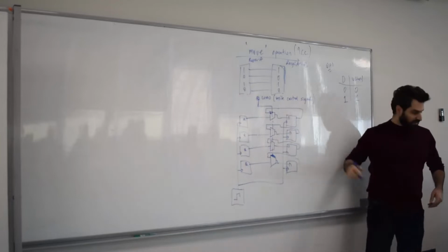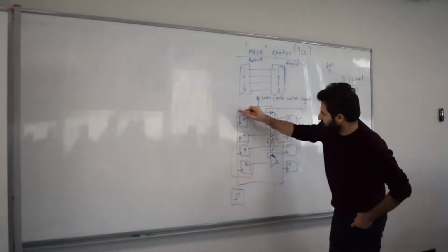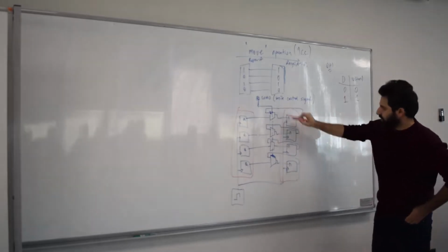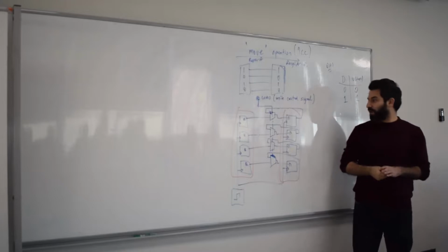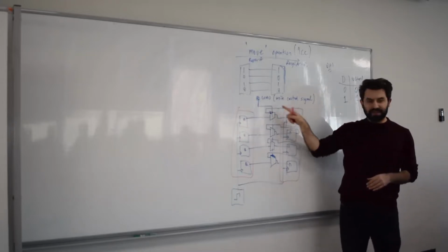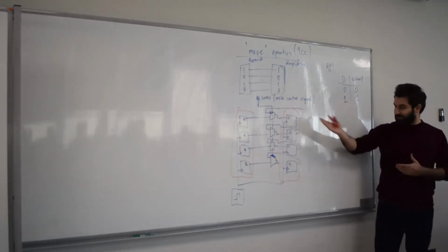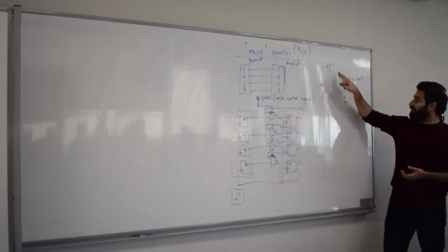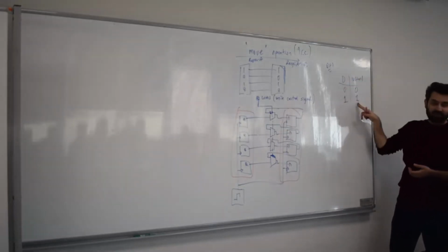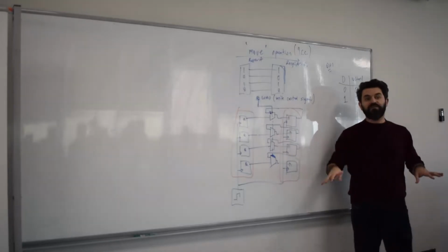Design your registers. These are registers, by the way, 4-bit registers. So this is your first register. This is your second register. Design those registers using JK flip-flops. Why not? And you would probably see that you don't need that feedback, because that feedback was there because of the deficiency of the D flip-flop. The deficiency being that a D flip-flop does not have Q-toggle in its state table. That was the problem with the D flip-flop. In JK and T, you don't have that problem.